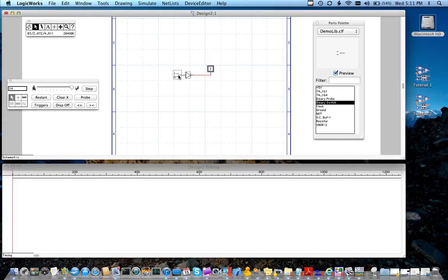from 0 to Z, which basically means high impedance. You can think of the high impedance as being undriven, and this allows you to set up multiple open collector or three-state devices, and they can drive a line to simulate a bus or wired AND logic. So this just demonstrates that the simulator has multiple states. I believe there's 13 states in all, and high impedance is one of them. So once again, there's a demonstration.